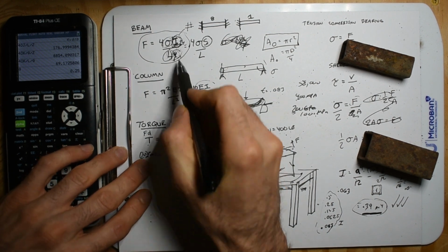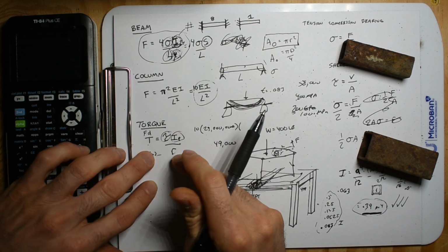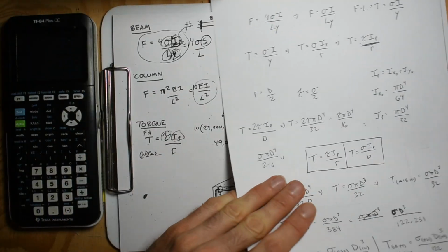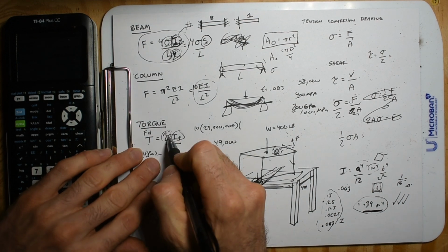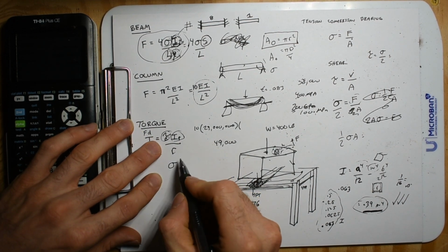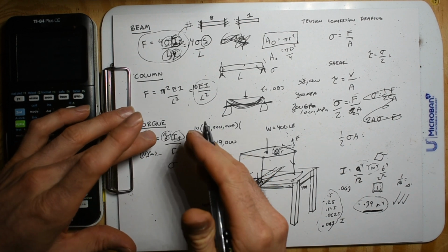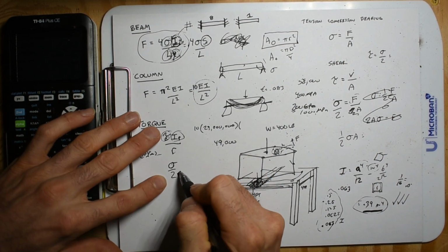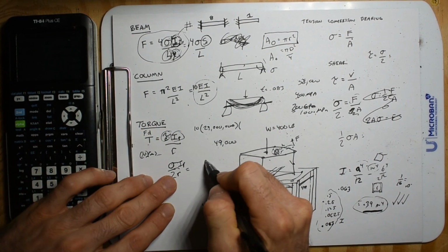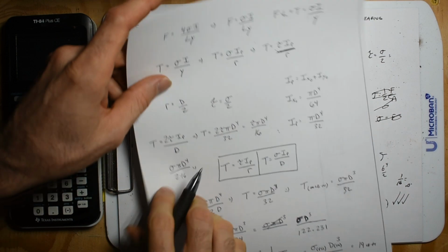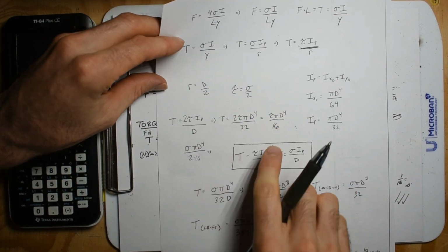You know what I mean? So we have one less length term down here, but the same things to make things simple can apply. I mean, we can say that this is stress. Shear stress is just like tensile stress divided by 2 for steel. So 2 times the radius is the diameter, so you can just go tensile stress times IP divided by the diameter. It's just kind of making life easy.